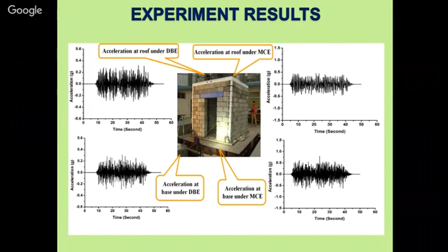We have also tested a 2-storied building, as you have seen in the test. In the 2-storied building, we kept a table, chair, even a vase on the upper story, and we observed during the test, after a huge impact type of loading, the furniture didn't move even a single mm on the first floor. So that means energy is not transferring from the ground to the second floor. If we go higher than the second floor, to the third floor, fourth floor, we are recommending this technology up to the fourth story only, because it is a load bearing type of structure.